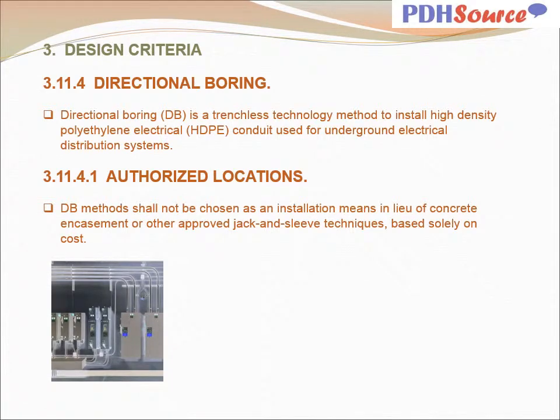Directional boring is a trenchless technology method to install high-density polyethylene (HDPE) electrical conduit used for underground electrical distribution systems. DB methods shall not be chosen as an installation means in lieu of concrete encasement or other approved jack and sleeve techniques based solely on cost.